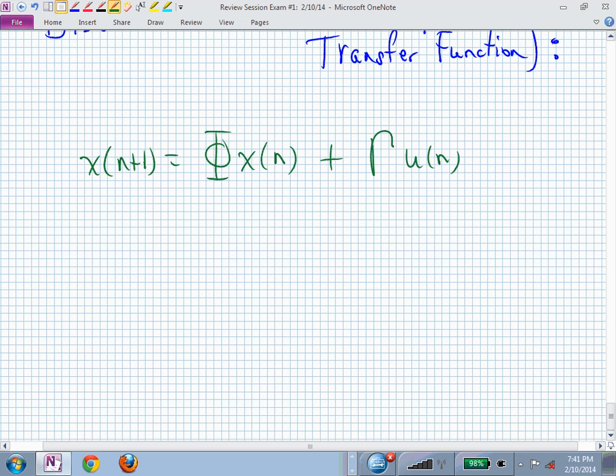And if u is two variables, it's a vector that's two tall, and one wide. It's 2 by 1. We now have a 2 by 1 entry for u of n, or a vector, scaling a gamma that's 10 rows tall and how wide? 2 columns wide. So gamma would be 10 by 2 if we had two inputs. In this class, a lot of times we just have one input, so gamma will probably be a single column. Is that clear? That's our dynamics.